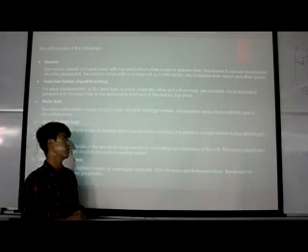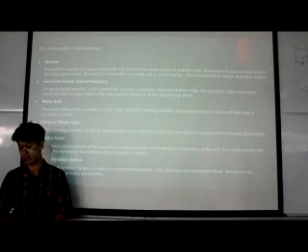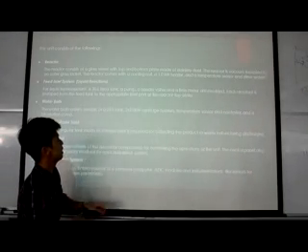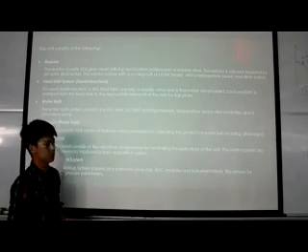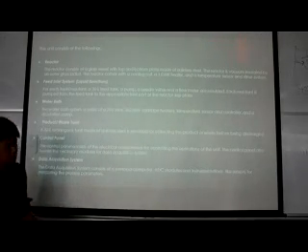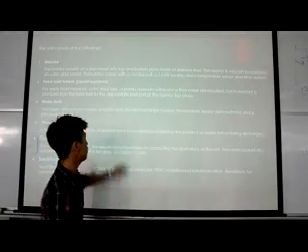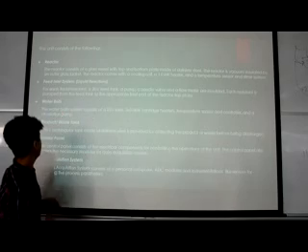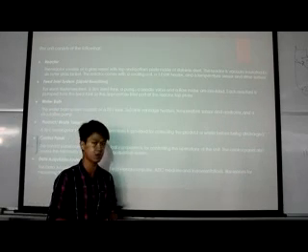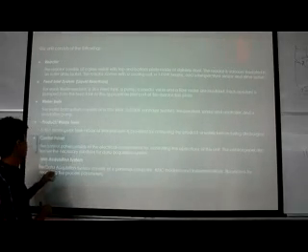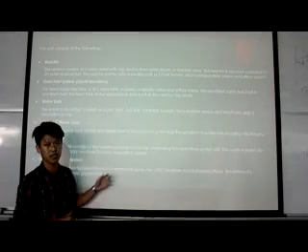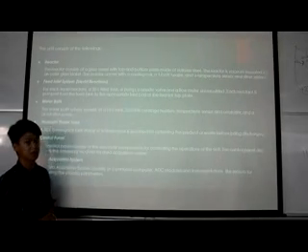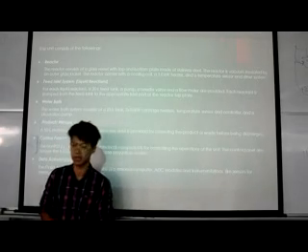Now, a batch reactor must consist of the reactor first. The reactor must have a tank with a bottom made of stainless steel, and it consists of the heater, temperature sensor and the stirrer system. Then we have the feed inlet system, whereby we have 2 feeds in this experiment, and a feed tank is about 20 liters large. After that we have the water bath, whereby the water will be used as a cooling water system. And the last will be the control panel as well as the data acquisition system. Basically, it's just a computer system whereby we can process the data and produce a graph and control the other process parameters such as temperature and the pressure of the reactor.